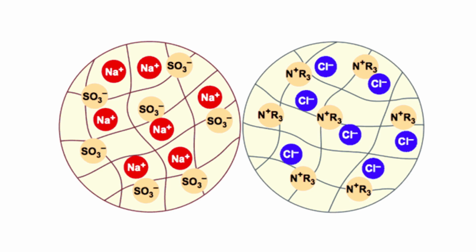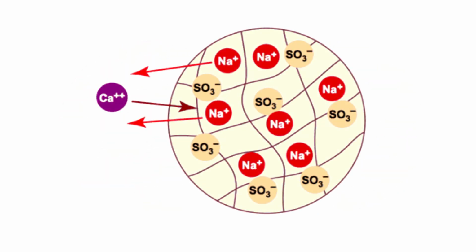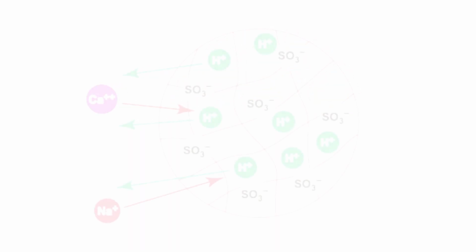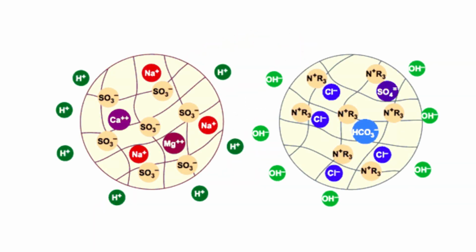Finally, what are ion exchange resins, and what is this process for? The ion exchange technology used for water treatment is a process in which a granular filtering medium composed of microspheres varying between 300 and 1200 microns, composed of polymers and electrically charged, aims to attract certain types of ions to itself, depending on the constitution of the end of the polymer chain.